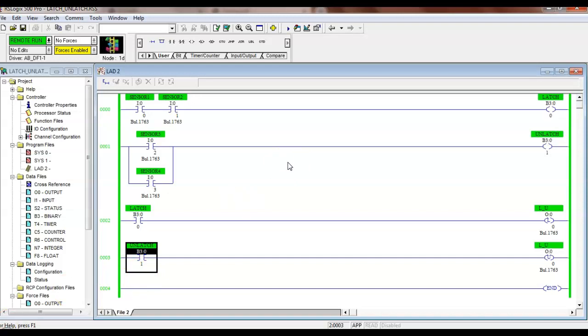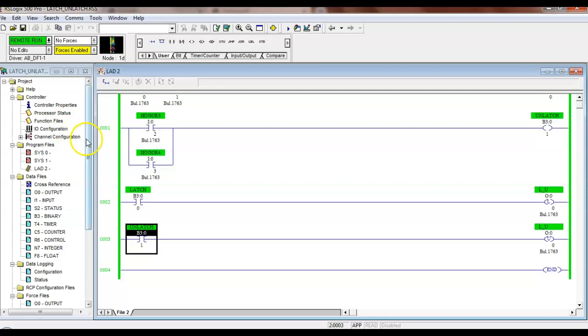So what we're going to look at now that we didn't cover in detail is something called forcing. Forcing is when you can energize an output and simulate an input. They still call it forcing without having anything connected. So I'm going to come up here. So notice my force is what? Can y'all see it right here? Enable. Then we have a table down here